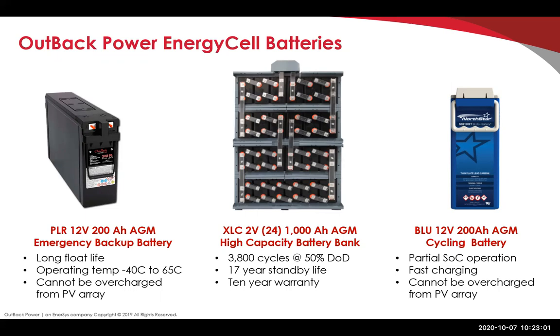The problem in the past has been that once you set those charge limits, they're there all the time, even once the battery is full. Once the battery is full, it doesn't matter. The energy will just flow over the battery. There's no longer a danger. Once the battery is full, you don't have to worry about overcharging it. Okay, so with these batteries, you don't have to worry about that. You can go big on solar, smaller on battery, and you're not going to overcharge the battery. Big benefit to these 2 batteries. And the blue batteries also, it's more of a cycling battery.